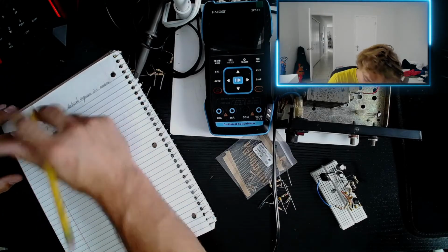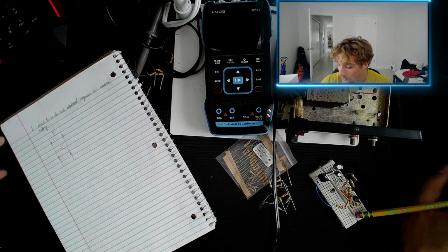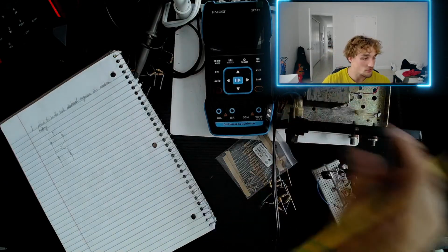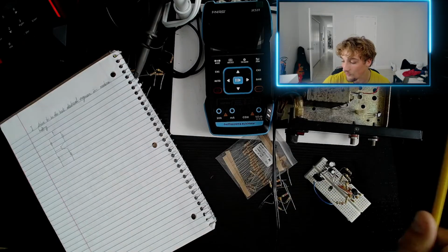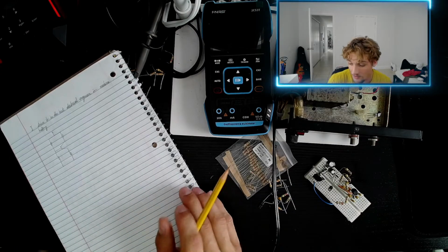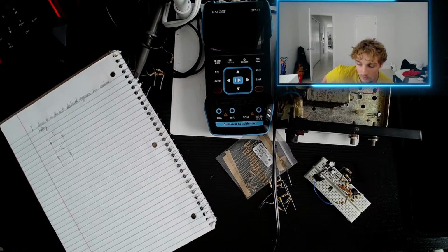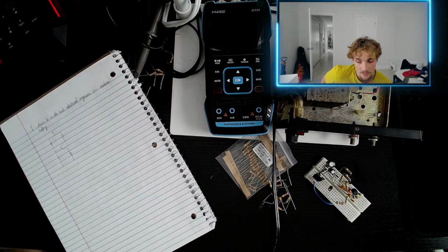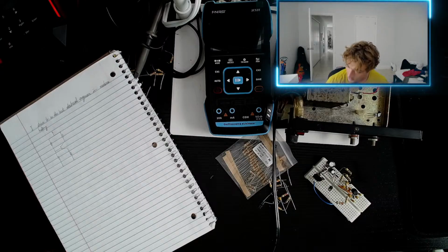All right, and I already have my supply configured. We're going to have this transformer. It's a step-down transformer from 120 volts AC to 20 volts AC through a full wave bridge rectifier. This is going to convert the 20 volts AC into 18 volts DC, with an approximate voltage drop of 2 volts to get us to that 18 volts DC.